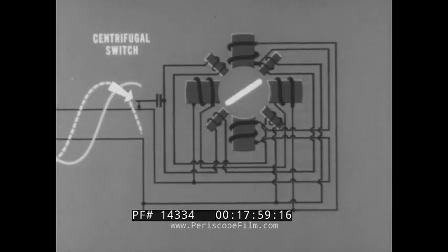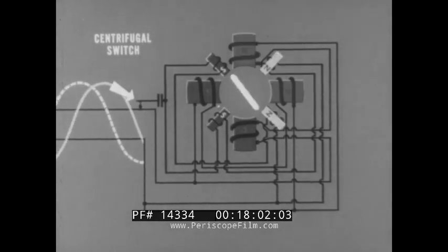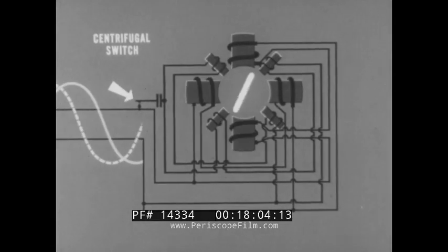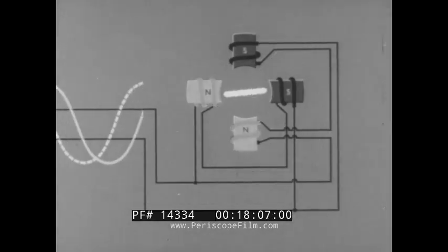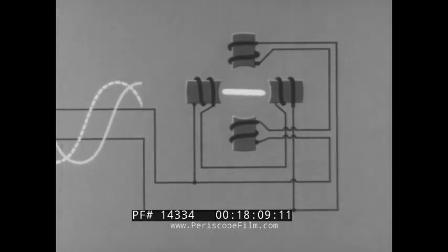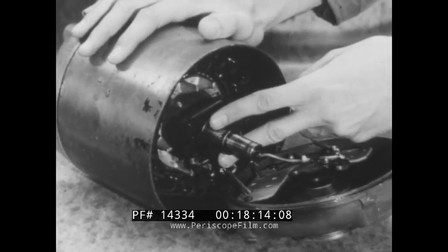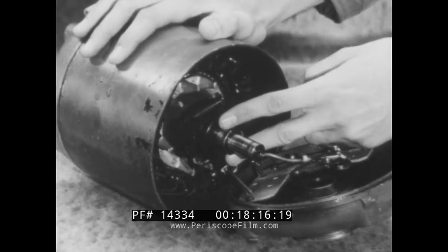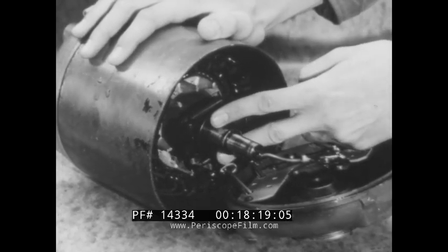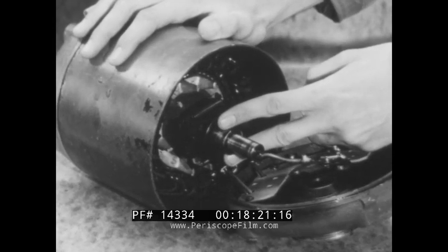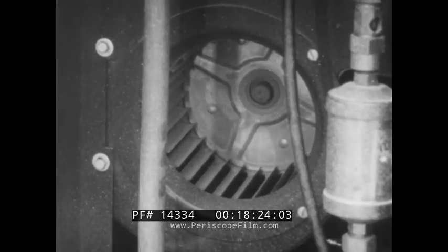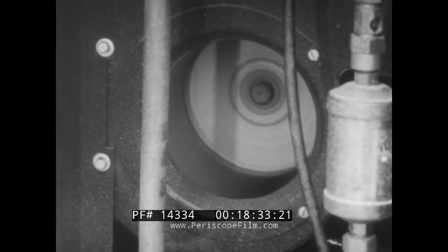This is a capacitor-start motor with a centrifugal switch. When the motor has attained 25% of its running speed, the centrifugal switch disconnects the starter windings. The centrifugal switch is mounted on the rotor shaft and is the type used on most split-phase motors. Since the greatest phase shift and relative motion is caused by the capacitor-start method, it is used in situations where good starting torque is an important consideration.